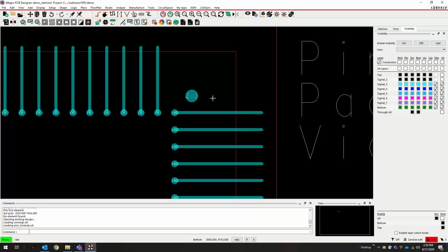There are different things to think about when you're breaking out the BGA. You have to think about the pin count of the device, and obviously the pitch of the pins, because as the pitch decreases, you have less space to break those traces out from the BGA area. BGAs have different patterns to them. Some have pins in the middle, some don't. As Jeff had mentioned, always go to your manufacturer when you're trying to determine what your pad sizes and traces need to be in these areas.